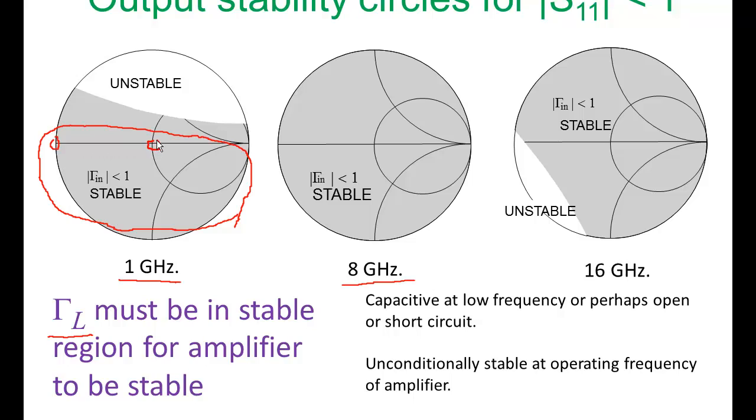And if we just had a pure resistance, in fact the pure resistance is anywhere along this line, we would have a stable amplifier. At high frequencies, again we must be in the shaded region, and in this case having a nice 50 ohm resistance would ensure stability. So too would an open circuit. But a short circuit would surely result in instability.